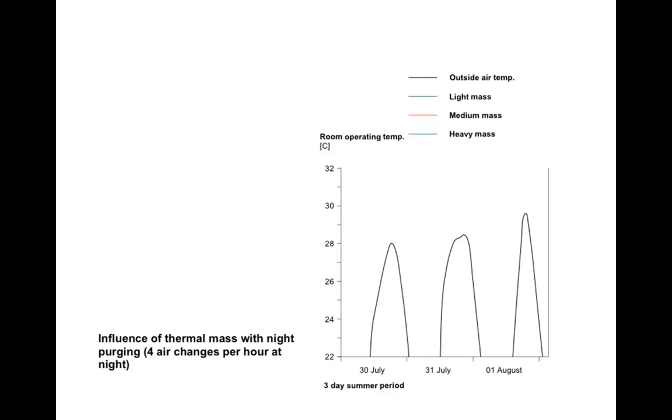That will absorb a lot of heat, a lot of energy. That plasterboard wall, which is hollow, will not store much heat. That is a plasterboard ceiling, so that will not store much heat. Before the Arts Tower was refurbished, that was a concrete ceiling, and that would store heat. So we're looking at elements of the building that can store heat.